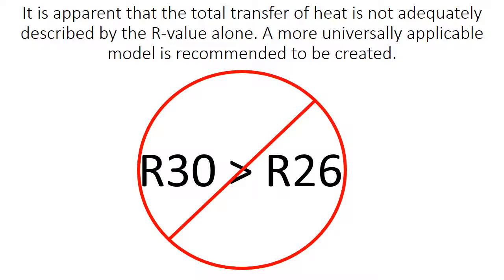So it is apparent from this that the R value alone does not dictate the quality of a building envelope, and that thermal mass needs to be evaluated and taken into consideration, because the cyclic time of day plays a great role on whether the amount of heat transfer leaving the house is constant, and if it is constant, what can be done to reduce it.